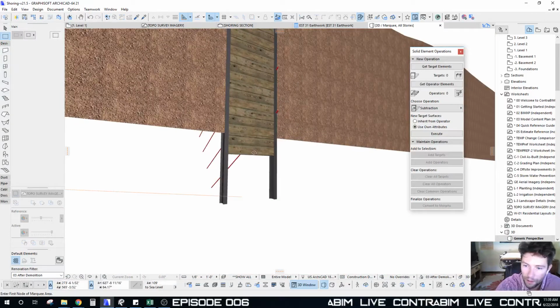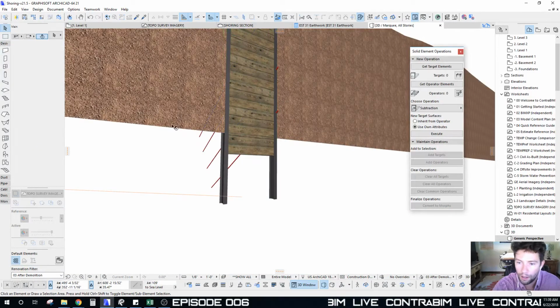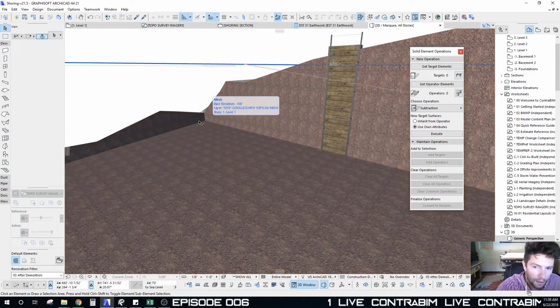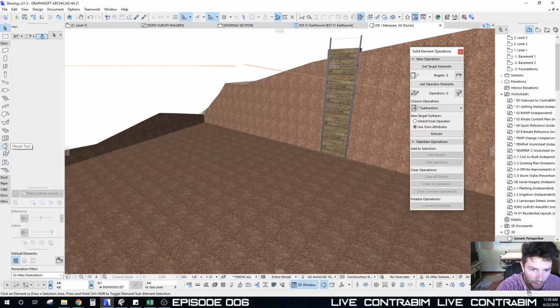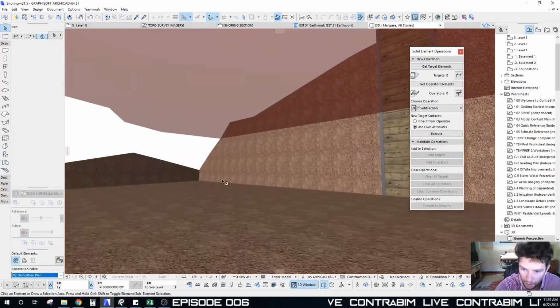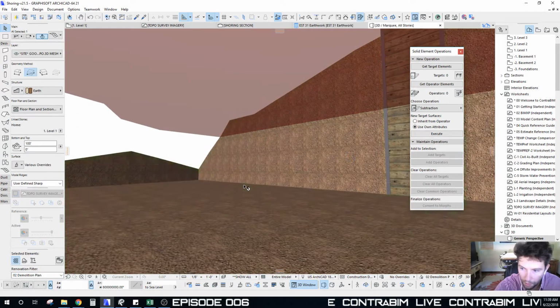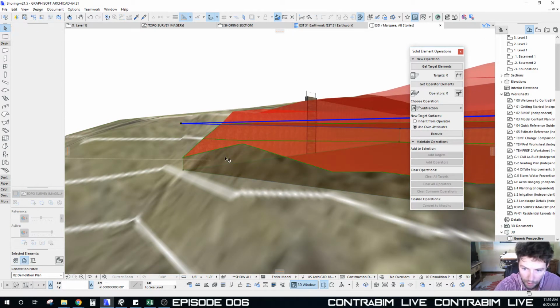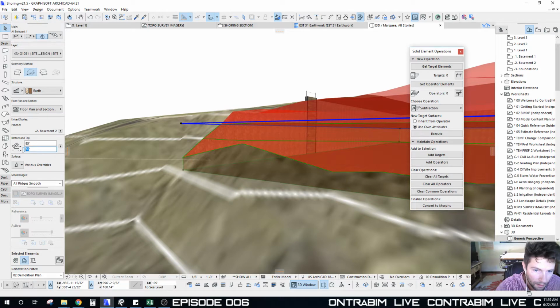We have a little bit extra down here below, but that volume for our basement, typically you're going to have some over excavation here also. So maybe if we bring back our demolition plan, we can come in here, grab our mesh there, and maybe we'll set this down to like 60.